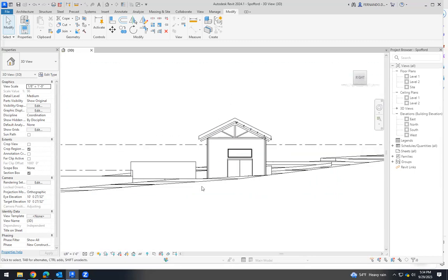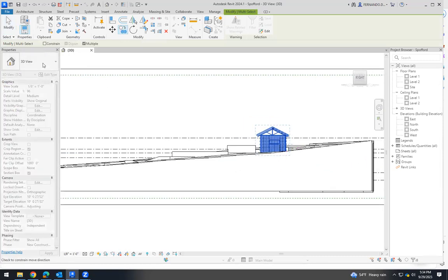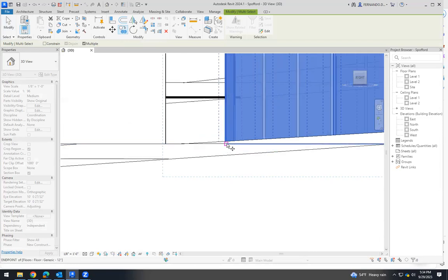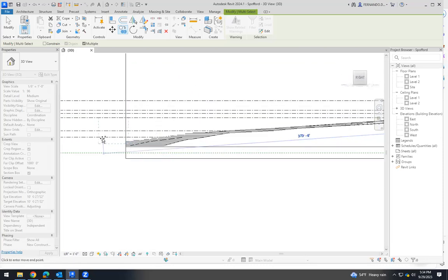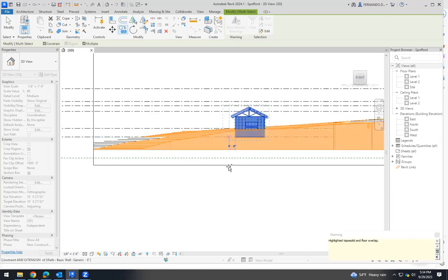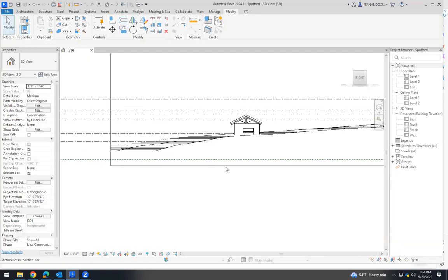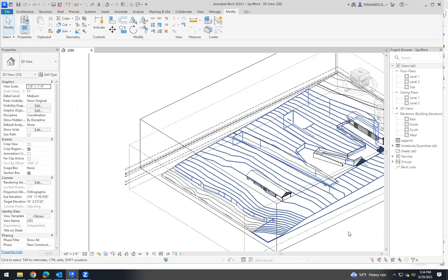Let's copy the building itself. If I click copy, if I remove the constraint and I select this disjoint selection, then I can copy this from the floor level. And I'm going to copy here on this level here. We have this warning, but I don't think it's too serious. Okay, this is the building itself.